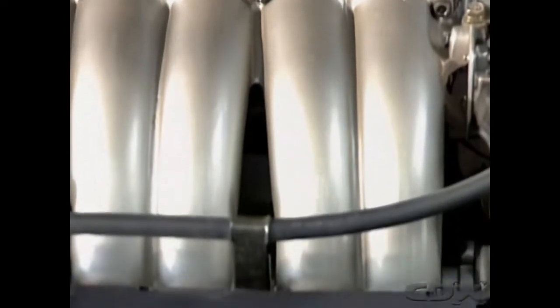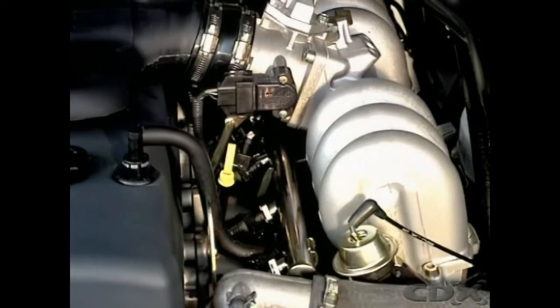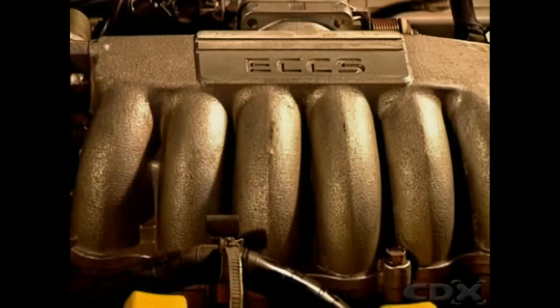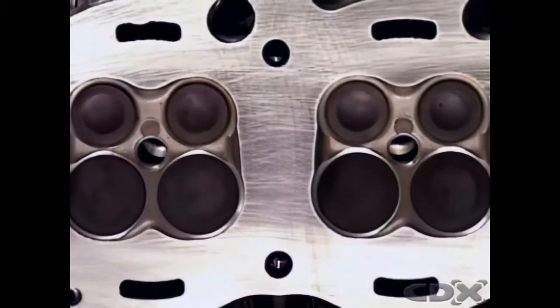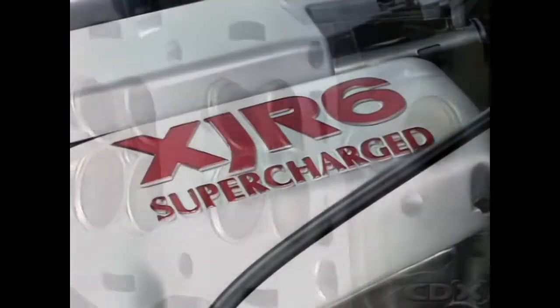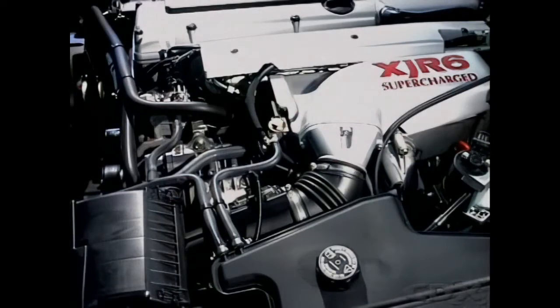The intake system can be crucial in increasing engine output. This can be done by increasing volumetric efficiency, that is, by increasing the amount of air that enters the cylinders. In fuel injection systems, this partly occurs automatically because of the increased efficiency of fuel injection compared to carburetted systems. Output can also be improved by using large, free-flowing intake manifolds and by using larger valves to admit more charge into the combustion chamber. Another method uses forced induction or supercharging to pressurize the intake system and force more air into the cylinders.